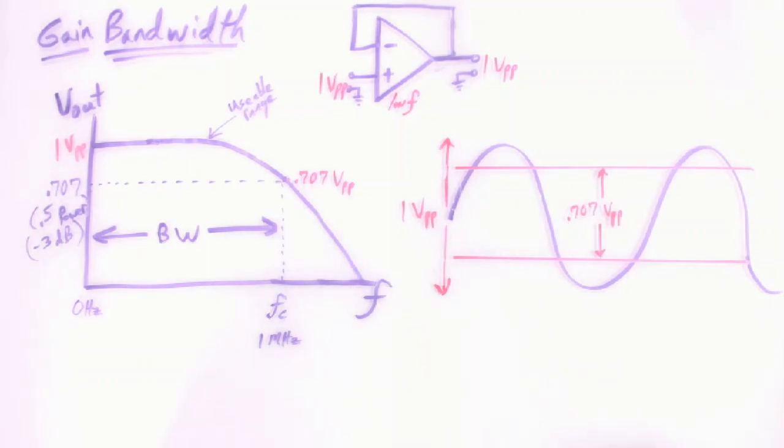Might look that up and do a calibration run on your Analog Discovery. Sometimes the offset can come from the op amp itself, in which case the calibration isn't the answer to the problem. You just have offset, and so you have to watch for that.